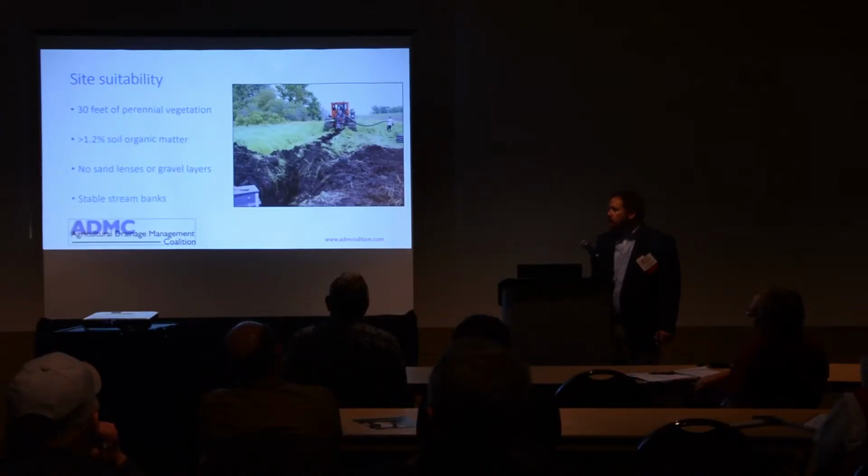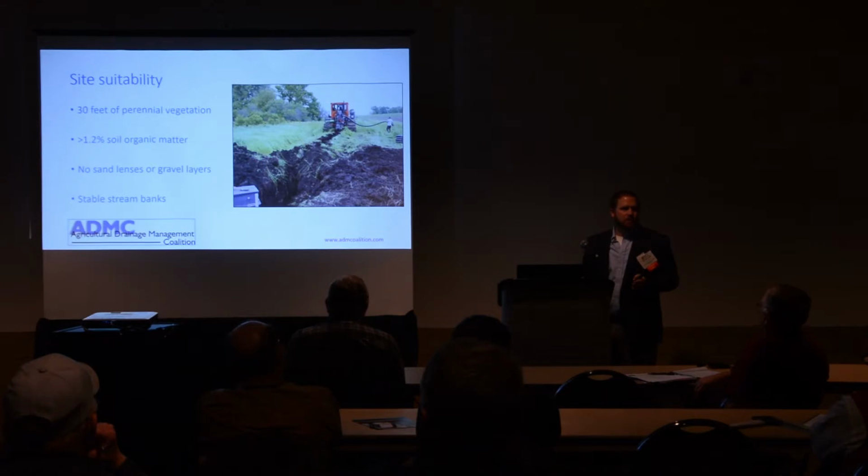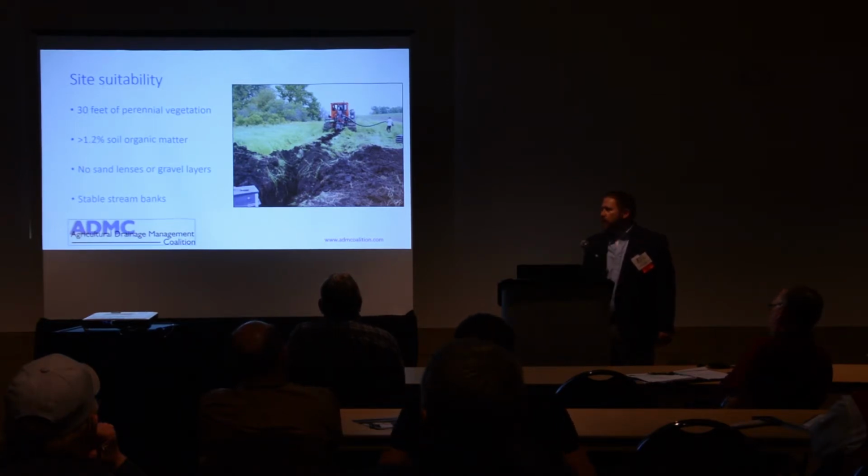I will say they did change the standard last year. Originally, it was written so anything over an 8-foot stream bank wouldn't be considered for a saturated buffer. But if we think a lot of our tile drained areas, that's the drainage district world, and how deep are those streams? They're a lot deeper than 8 feet generally, but they have very stable stream banks because they're engineered and redesigned on a regular interval there when they clean them out. So they typically have stable stream banks, and so those are areas that we want to be able to get treatment if we could.